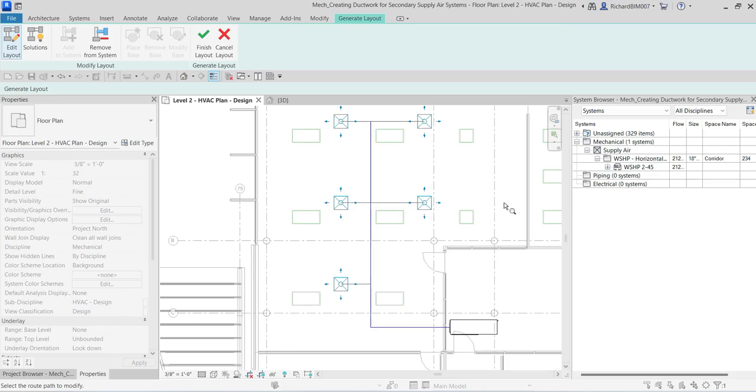All right. And then after that, we are now going to finish this one. Just be careful not to drag the main duct too close to the diffusers. If there is not enough room for the software to create the necessary fittings, you'll get an error in a later step. So that's why you shouldn't move this very close to your supply diffuser. Okay, and then we're going to finish it. So let's select here, Finish, click that.